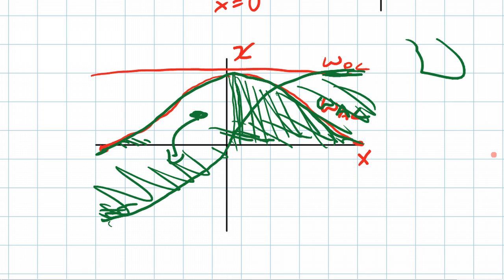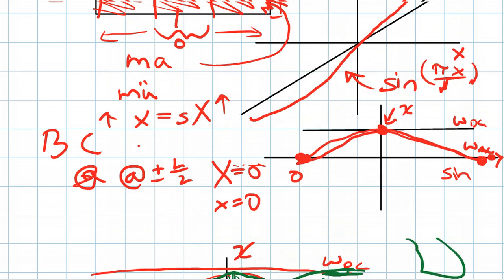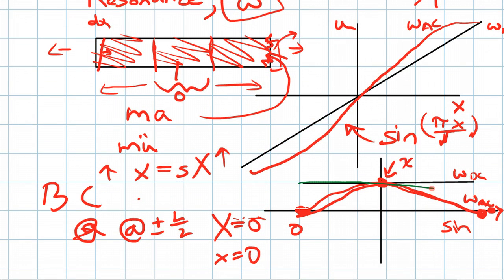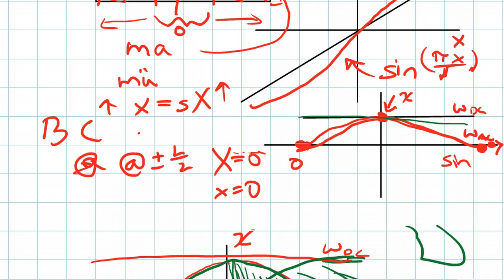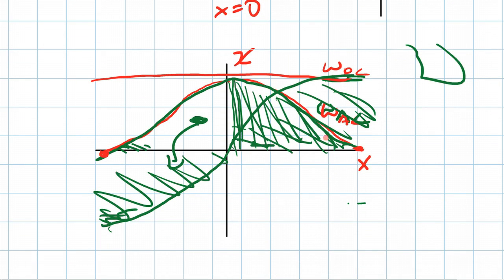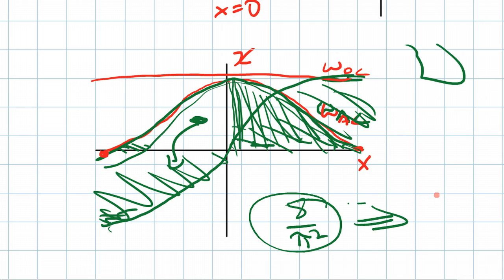I believe this wraps up this topic of why we can't use the spring constant, because the spring constant is relative to a constant displacement, a constant strain. But in reality, we have this sinusoidal strain, which is going to need some modifications. So we're going to see there's something like an 8 over pi squared modification to this spring constant, which was